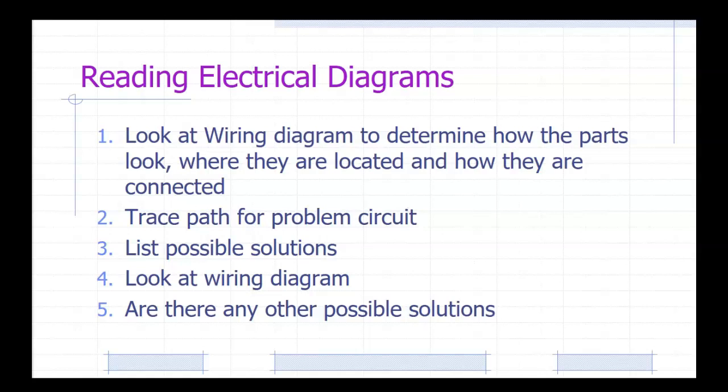It could be as simple as looking for a loose wire, because what happens in industrial is wires do come loose. What do you have to do? You have to trace it down. What happens in pneumatics and hydraulics? Eventually a hose will crack or a pipe will crack. What do you do? You got to go run it down and replace it.